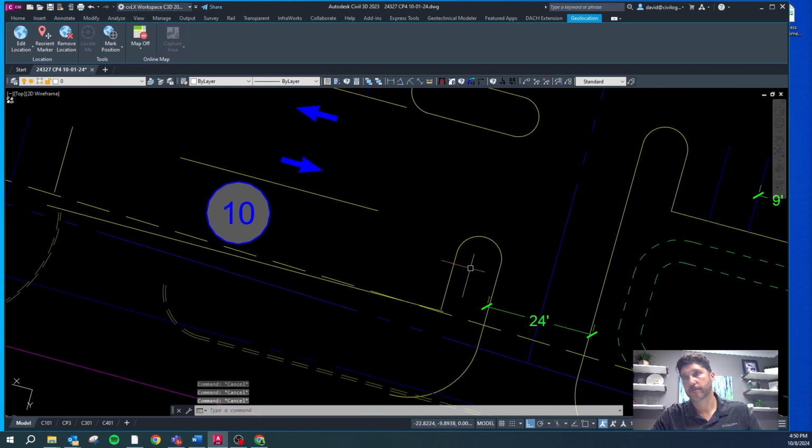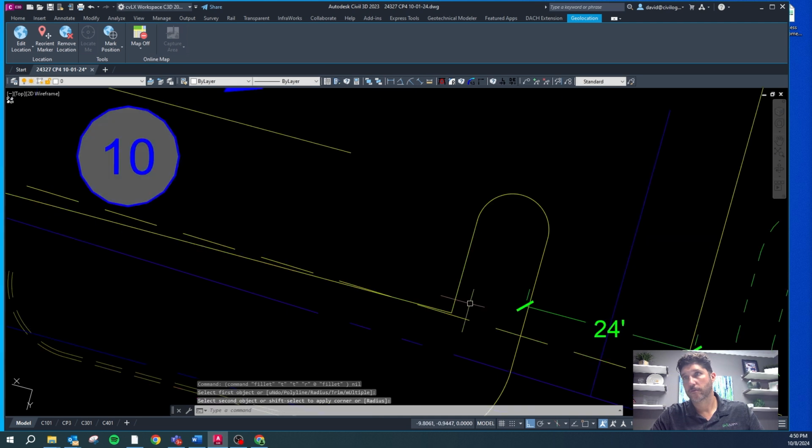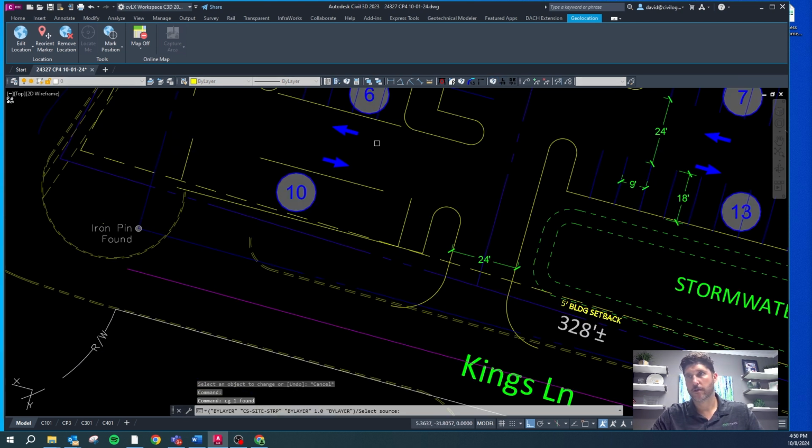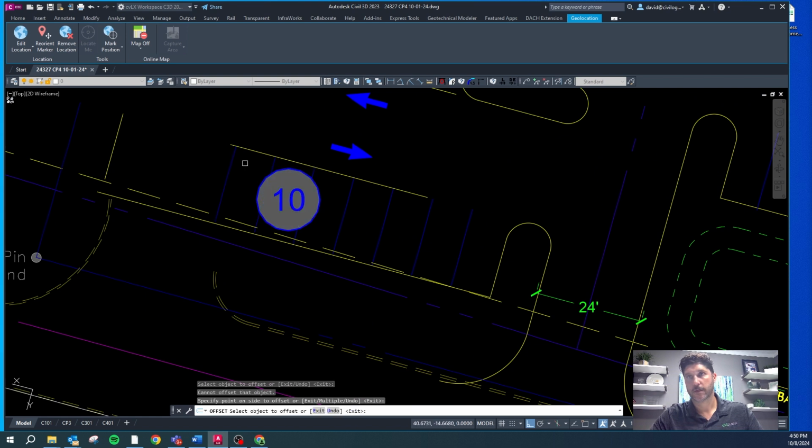And so we'll make a nice clean line there. We'll measure 9. We'll do this to 18, lengthen to 18. Put that on the proper layer, and then we can start offsetting by 9 to have these spaces going across here.